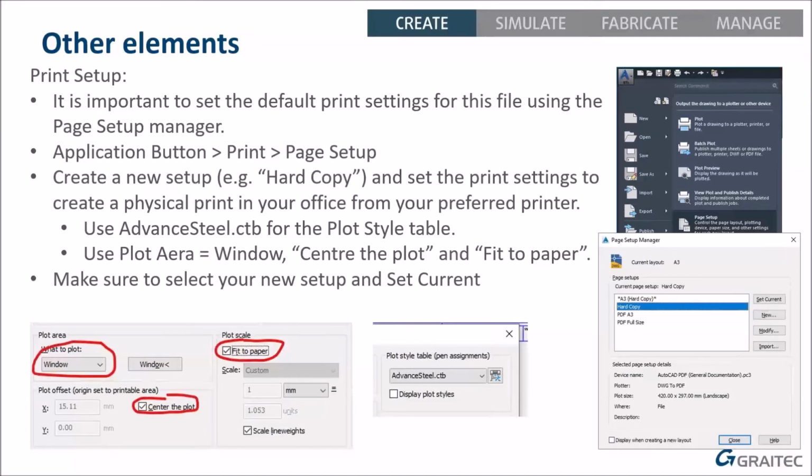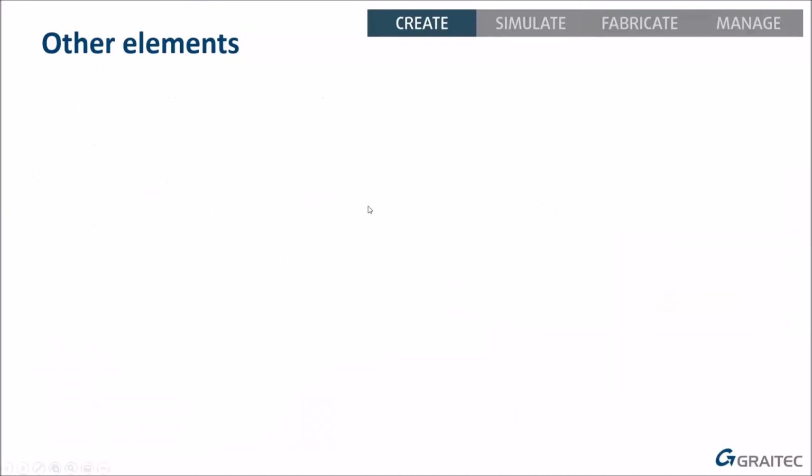And then if you want the PDF, you choose the files, add to batch plot, choose a plotter, PDF, go. And it will use all the rest of the settings correctly anyway. If you don't set those up properly, you could get messy or poor batch printing. There's a couple of other things that might crop up.